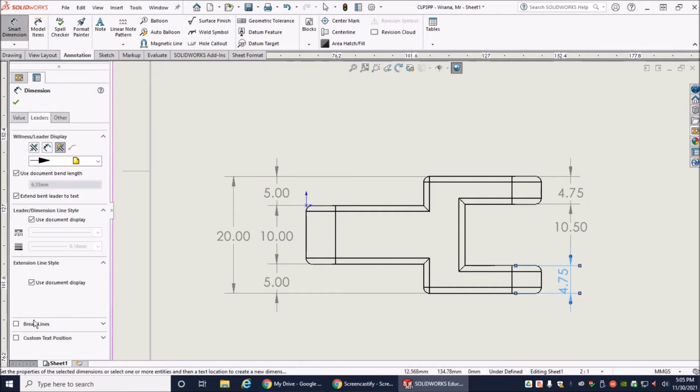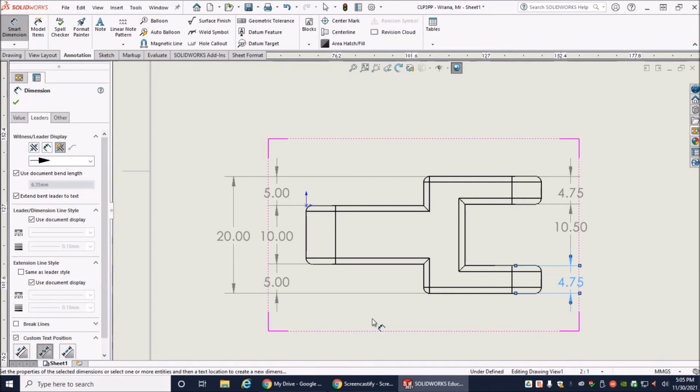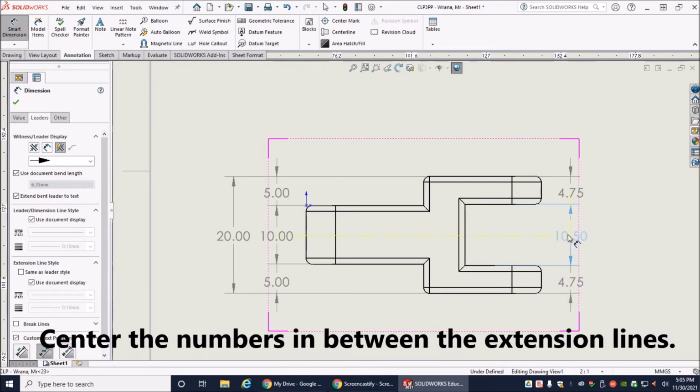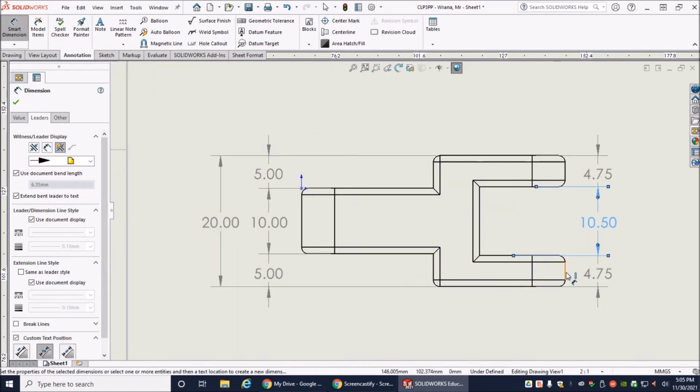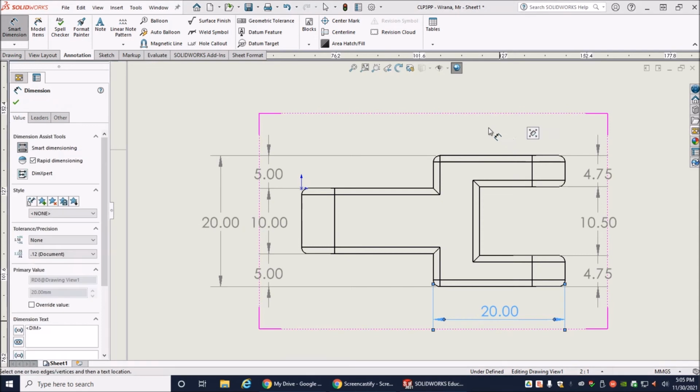And then just the same thing. It's all I'm doing. Okay, let's bring this down just a little bit. Looks good. So I got the side measurements. Now I want to go ahead and get the overall length measurements from this shoulder to the end. And I only need one. I don't need to do it to the top, just to the bottom. Don't need it up here because this stuff is parallel. The only time you need to put a measurement up there at the top is if they are different.